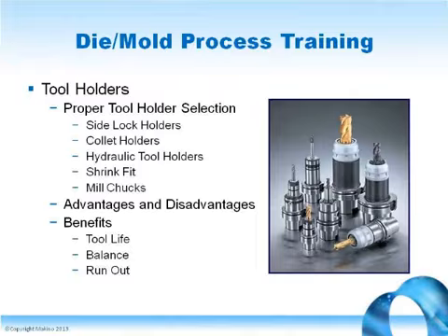Tooling is the most costly portion of the machining process. Benefits of proper tool holder selection and application will be that tool life will be increased, effective tool life is more predictable, tooling costs can be reduced, balance will be acceptable, and runout will also be acceptable.